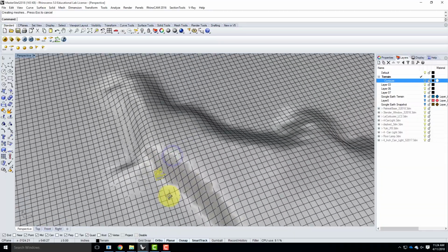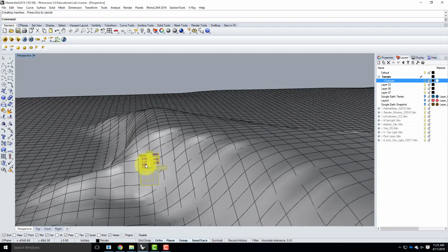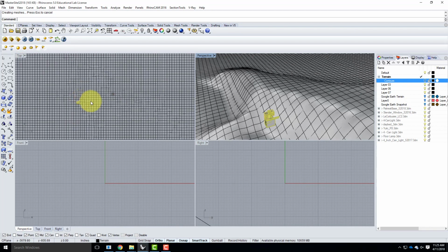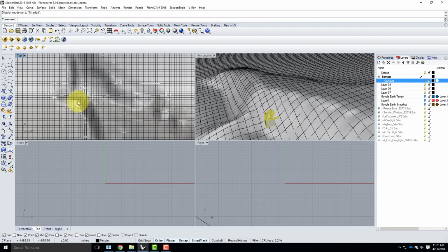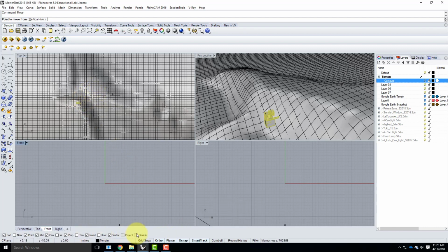And it's kind of floating. It's not really where I want it just yet. And now I can start to work with it. So sometimes it's helpful to do it in perspective. Sometimes it's helpful to do it when you have multiple views. Sometimes if you change the top view to be shaded or rendered, you can kind of help yourself out a little bit by seeing the shadows. And so I'm going to start by moving. And I'm actually going to turn off for right now all of my object snaps. I'm going to disable them so that I can just start to work and get it placed in site.